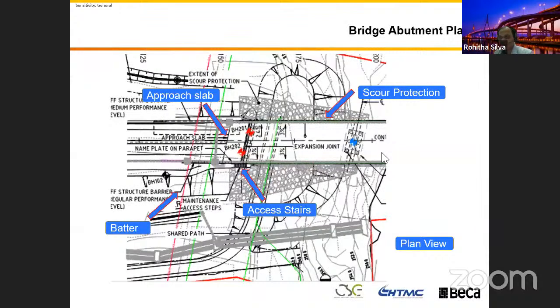If you do construction in Bangkok, for example, if you build a bridge in a subsoil area, these abutment structures, which we call transition structures, bearing units, different names designers call them, could be as long as 100 meters. The settlement around here is about 15 to 20 millimeters, but depending on the ground condition, you may have a long-term differential settlement of 200 to 300 millimeters, even more.